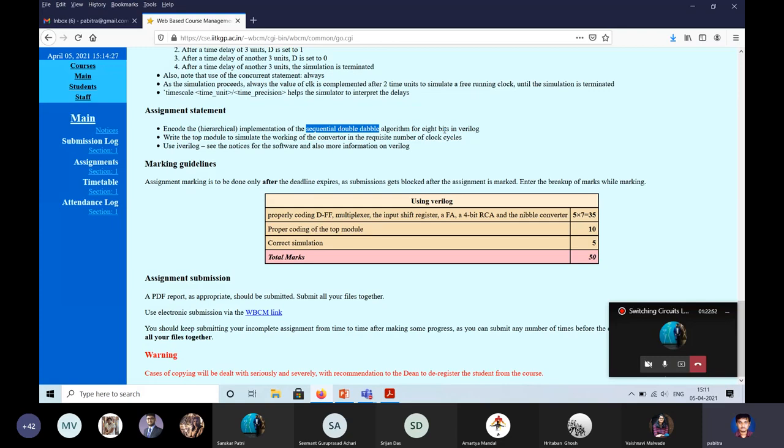Okay, and then just like there is a main program, there is a top module. It's called a top module. So you have to write a top module. Usually your display statements are there in the top module, and your dump statements, where you write the simulation for the test bench, dump file statements are also in the top module. Okay, and the top module will call the other modules, all the circuit modules.